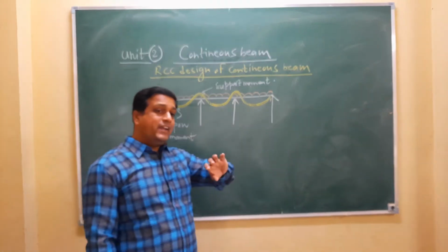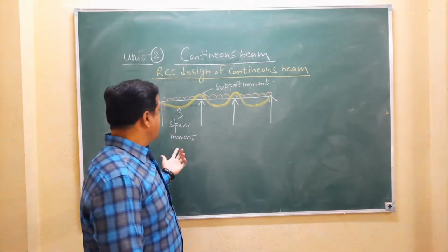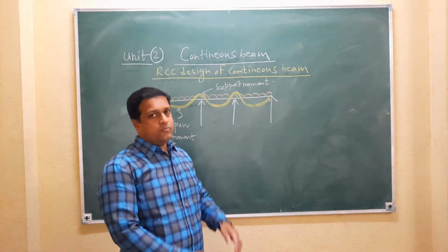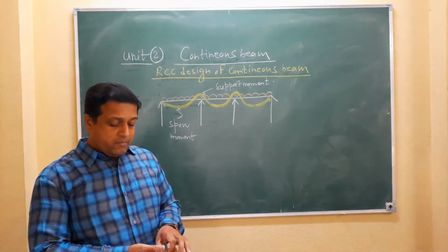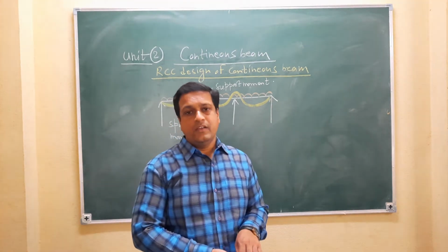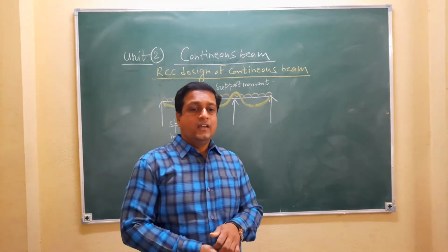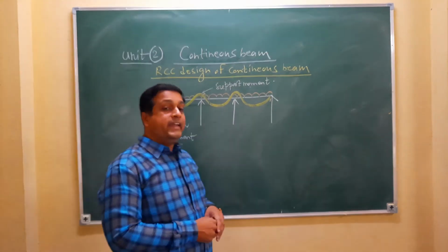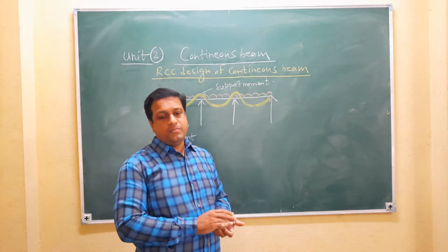So while designing the continuous beam, you have to consider these two types of moments, span moment as well as support moment. That means before going to design, the main thing is how to analyze the continuous beam. The important, interesting part of this unit is analysis of continuous beam.